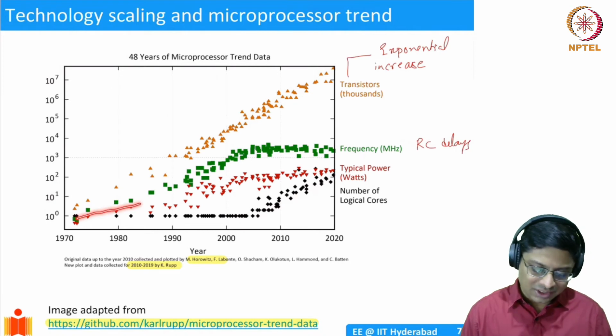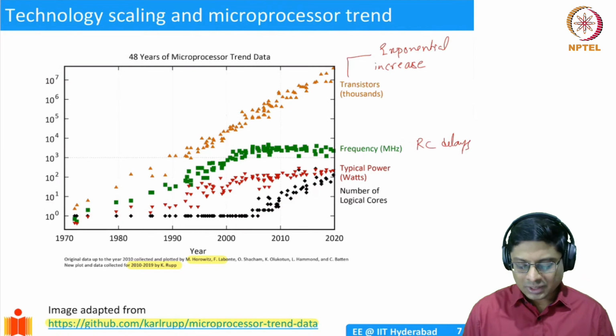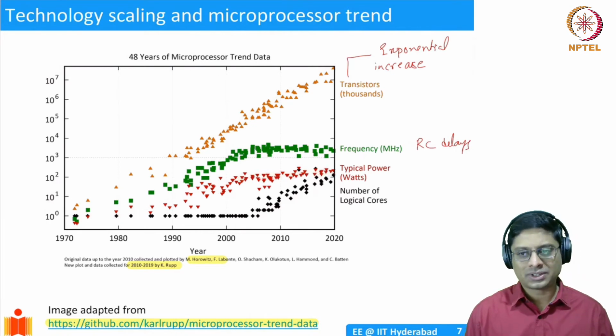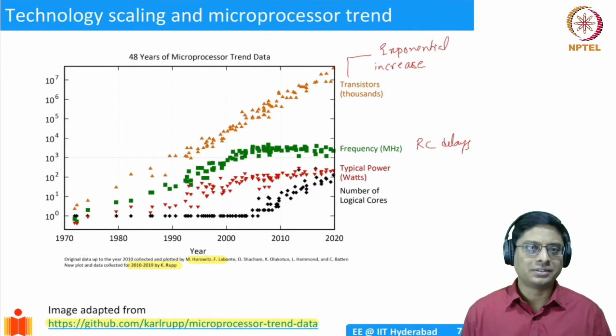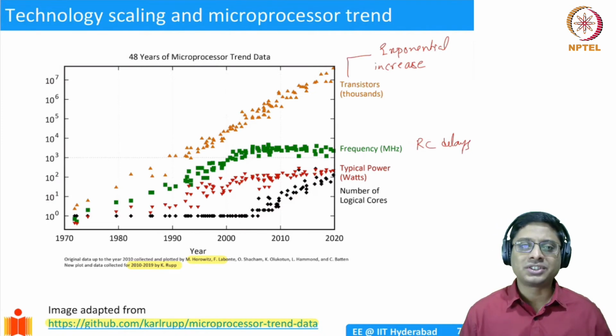You see that initially power was increasing because we were increasing the number of transistors. But then after some time, we are not able to increase the capacity more. The reason is if you have more power dissipation, you're heating up your silicon. Once you heat up silicon, we know all bad things will happen. Mobility can reduce, and threshold voltages can shift. Whatever transistors or circuits you have designed so carefully might not work as you want them. So we don't like them to be heated.